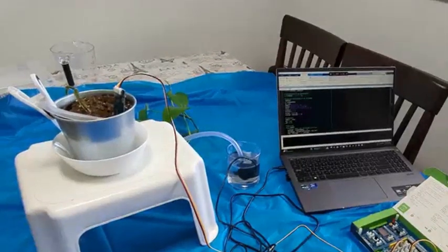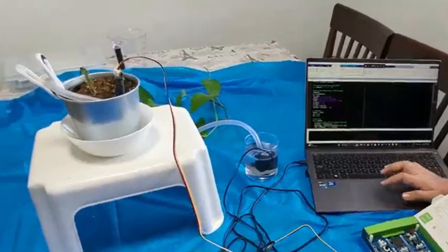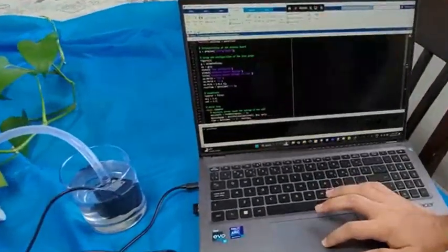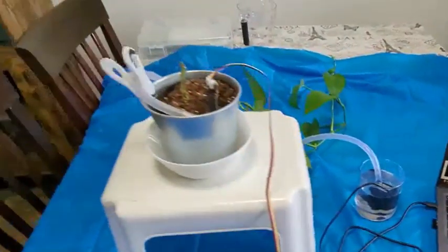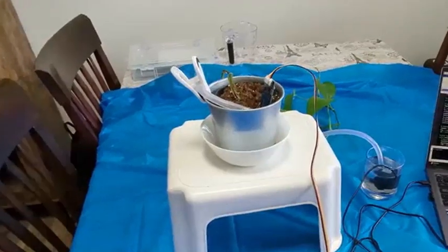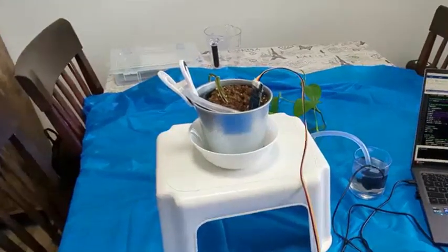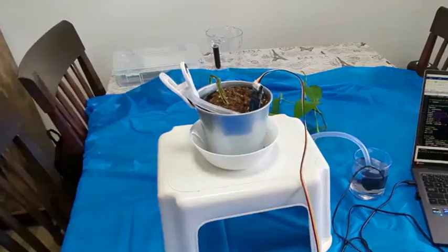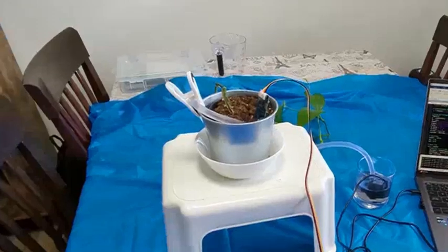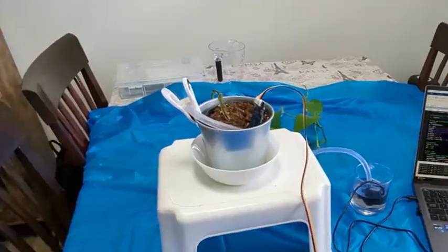When the run button is pressed in MATLAB, a moisture sensor is used to detect the voltage of the soil. Depending on the state of the soil, the system checks the conditions to determine if the plant has to be watered or not. If the voltage is greater than the dry and wet threshold, the system will water the plant. Once it's less than or equal to the wet threshold, it will stop watering the plant. Since the plant was initially dry, water was sent to its soil.